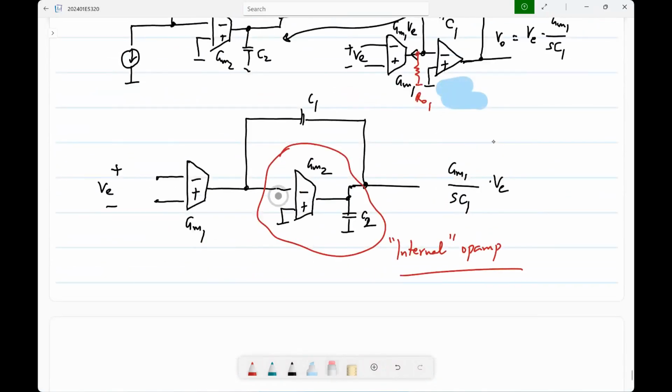Now in reality, what happens? This voltage will be non-zero, but it will be smaller than the output. That smaller voltage appears across RO1. So now the input voltage is non-zero, but smaller than what it was before. Okay, so we have got some improvement. We'll of course do the quantitative analysis. I think you already have enough analysis knowledge from analog systems and analog circuits to analyze this to death, but you should also have an intuitive picture of where this comes about.